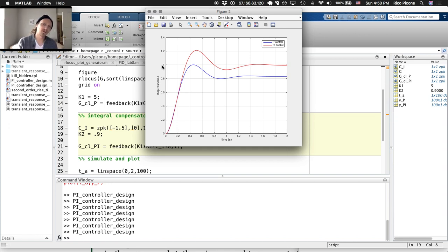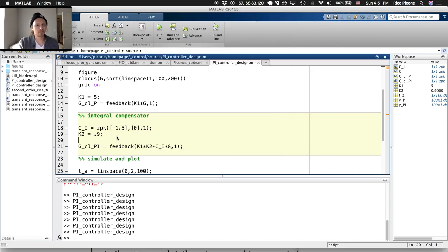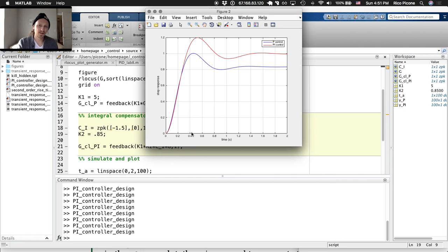Okay, so we got closer. Our transient response is similar to our original. I'd say, without doing step info, just sort of looking here, yeah, a little over 21% overshoot. So maybe we could bump it down to like 0.88. Like, I don't know, maybe 0.85. It's really hard to say at this point. I think we just nailed it.